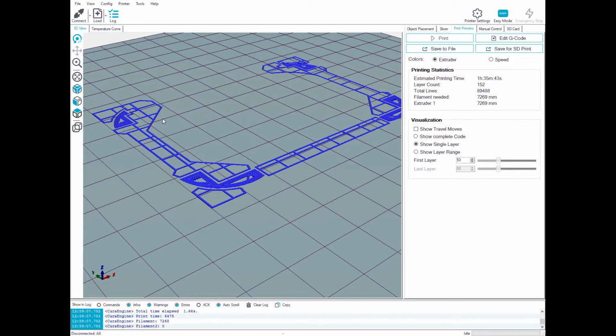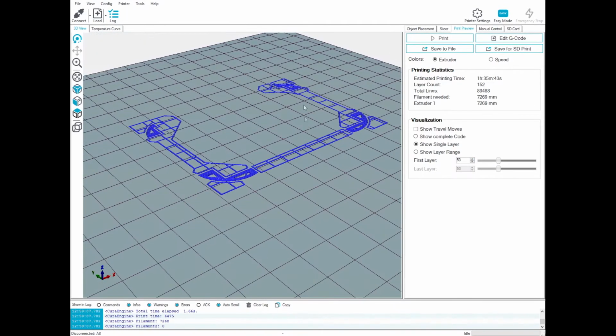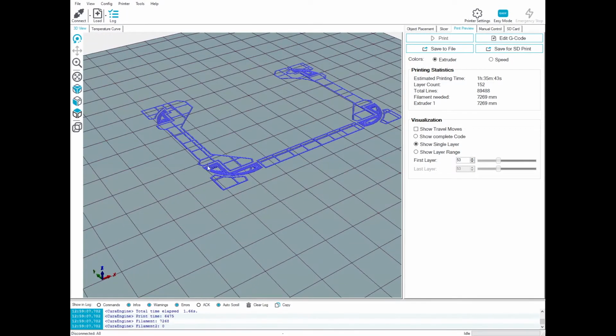So here's the first kind of cross-sectional cut showing support structure. You can see these little 90-degree semicircles here in the corner. That's the actual part that's going to be kept. And all of these very sparse, single outlined, automatically generated support structures here are meant to be broken away, loosely attached. Believe it or not, even though these little visual representations of the plastic glob have space between them and the frame, they'll be lightly attached whenever that's printed.